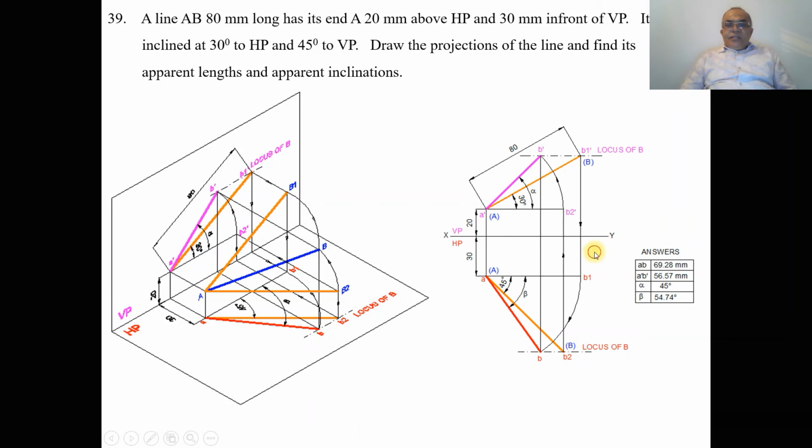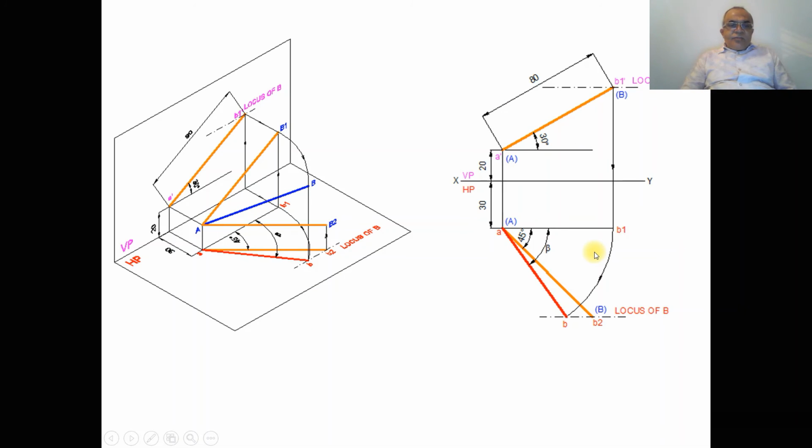So in the next position, we have shown how individually we can do it. This is just the explanation we have given there, and we have split that, considering it individually step by step. So we have considered initially the position of the front view true length, and we have rotated it such that it is going to cut the locus of B in the top view.